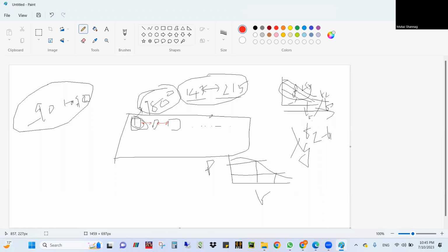For example, you have a unit cell size during the simulation, correct? That is the interelement spacing between them. So how it works is, you have this unit cell, for example, let's say lambda over 2. In principle, you have a unit cell like this, and a unit cell like this. Center to center is your lambda over 2.